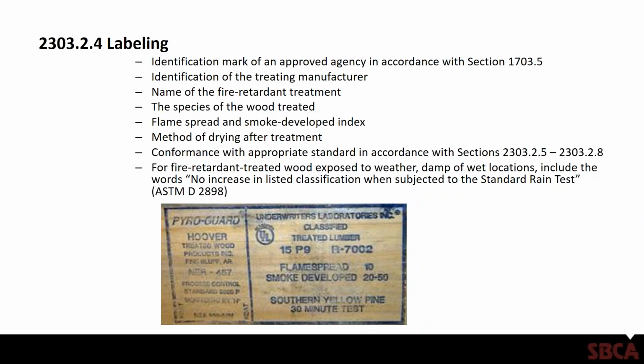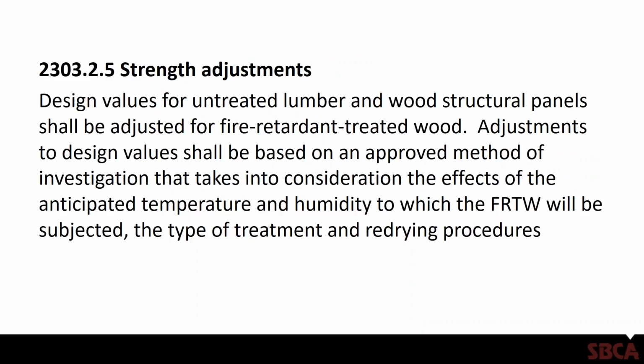And then finally, if this product were to be used in applications that are exposed to weather, damp, or wet locations, it needs to include the phrase, no increase in listed classification when subjected to the standard rain test, ASTM D2898. Again, that would be for an exterior application. In this case, this doesn't have that on there. So in looking at it, one would assume, and rightfully so, that we are looking at an interior application only.